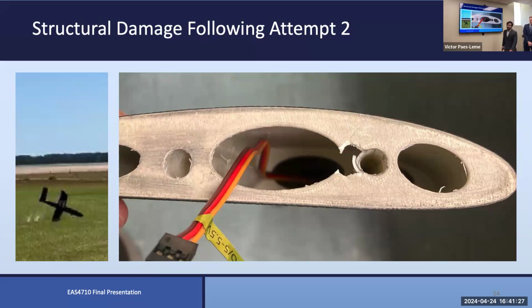So for all our friends in structures that are asking yourselves, with such a high margin of safety, why did you decide to go for the carbon fiber on the skin? As we mentioned, one of our concerns was the damage that the plane could sustain, not during a very severe crash where the entirety of the plane nosedived onto the ground, as there is very little we can do about that, but about these little nicks, twists, and landings that may occur.